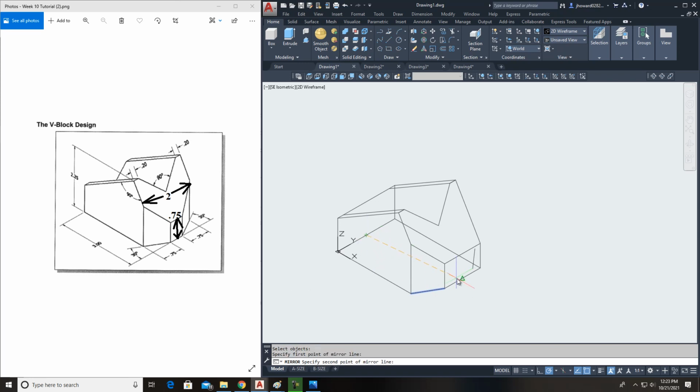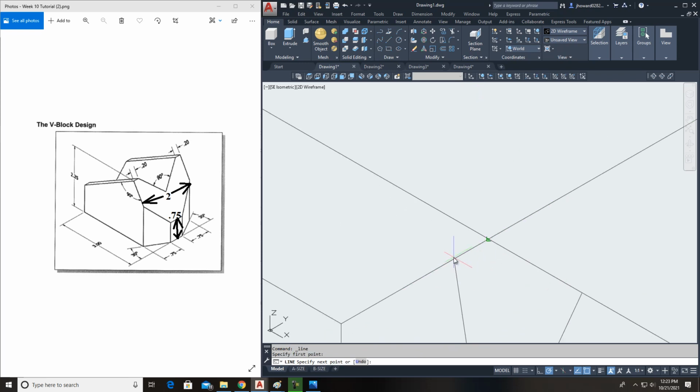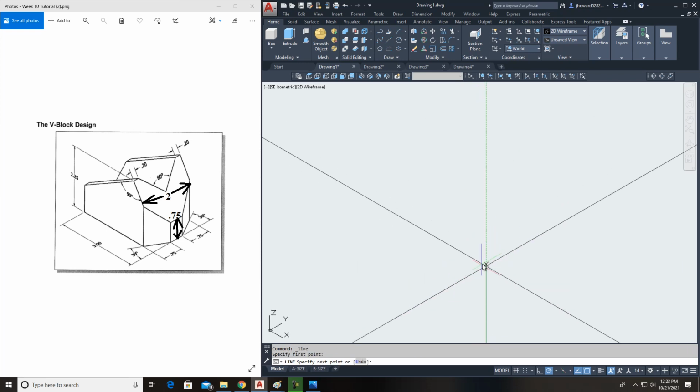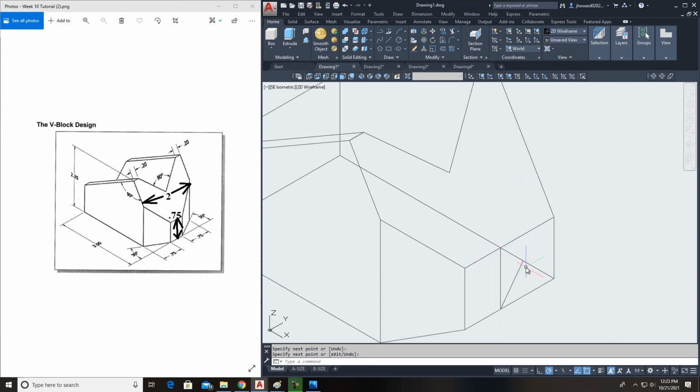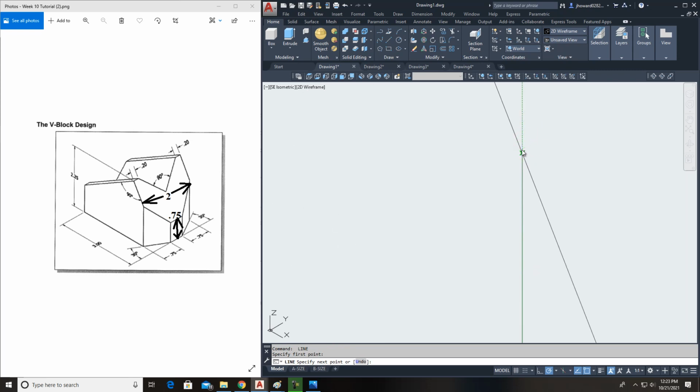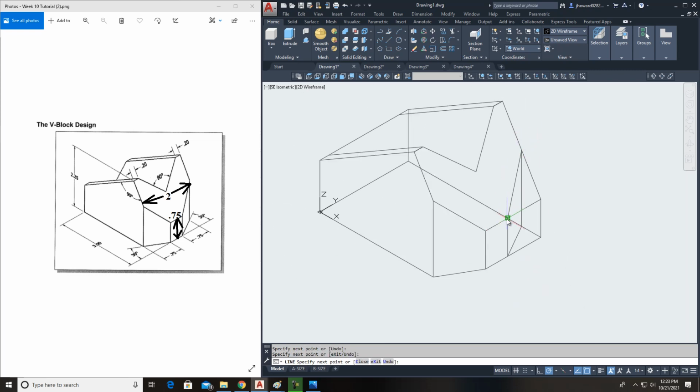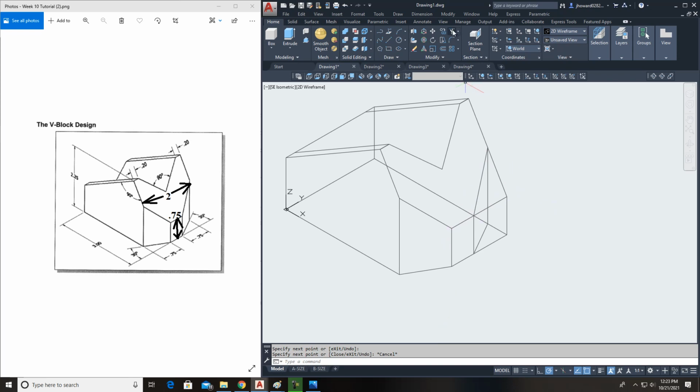You have to have the full line, and I hit it perpendicular. Enter. That looks a lot better. And you can go ahead and just make sure that you're snapping to that line perpendicular. Make sure this one's coming all the way up here. Make sure it's just catching there, and then bring it down to there. And then you want to trim everything out. Okay?